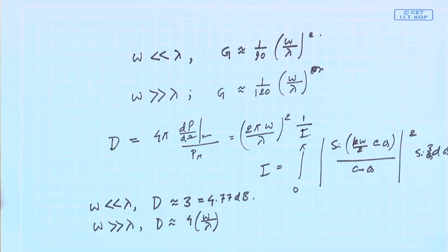So, that is why it is not much, and there are methods by which people use a higher dielectric constant substrate, or increase the thickness of the substrate, or cut holes or slots, or add reactive components, etc. Various people make various better and better designs.